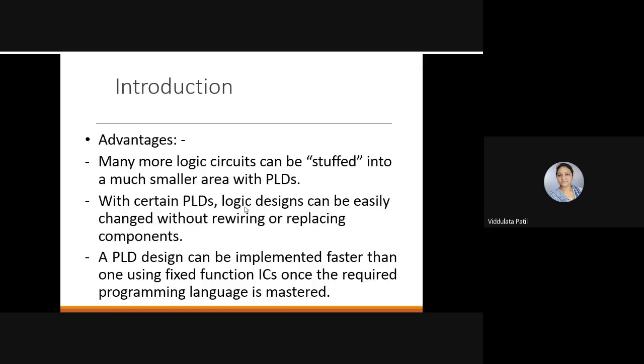A PLD design can be implemented faster than one using fixed function ICs once the required programming language is mastered. If we use fixed function ICs to design for a particular application, we need many other components besides that fixed function IC. But with a programmable logic device, in one component only, we can build a similar function circuit.